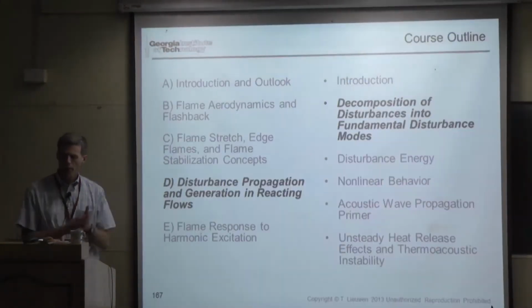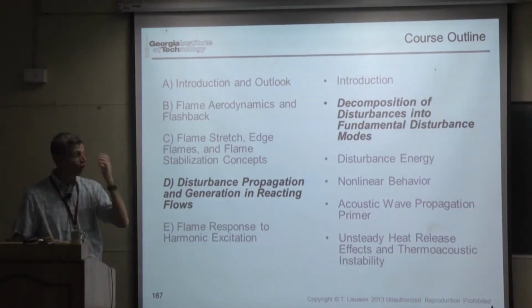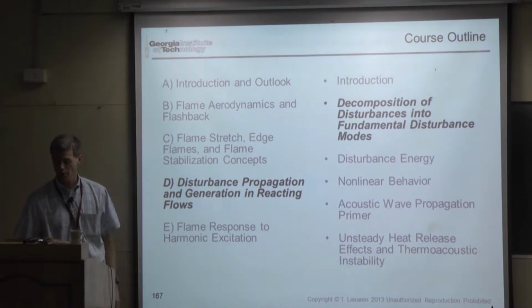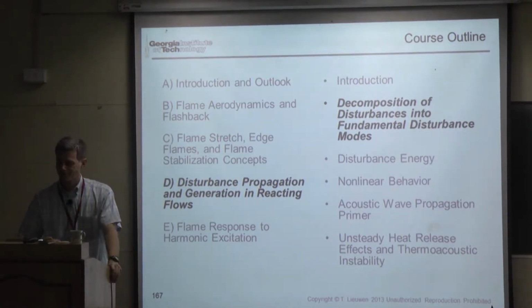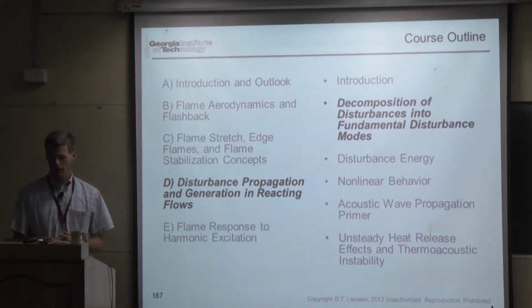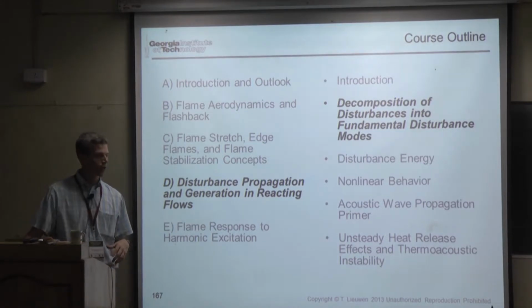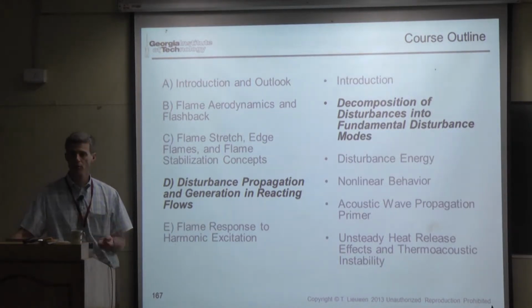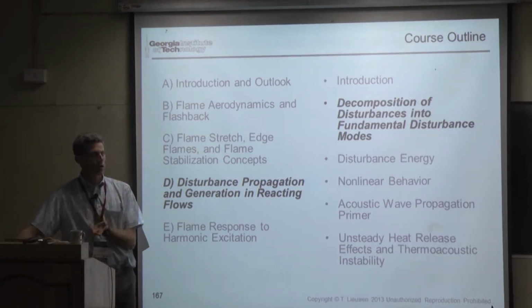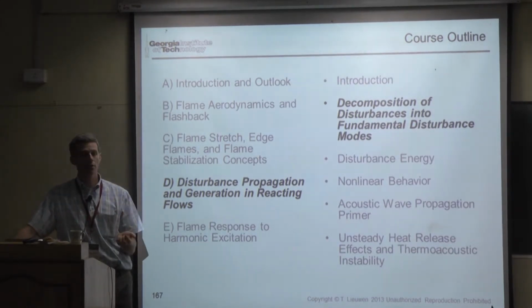And what I want to talk about are fundamental disturbance modes. So ultimately, you can see combustion instabilities are associated with disturbances. I've used the word acoustic a lot, and so part of those disturbances are acoustic, but they also involve interactions with vortical disturbances, and oftentimes these acoustic waves are exciting hydrodynamic instabilities of the flow.